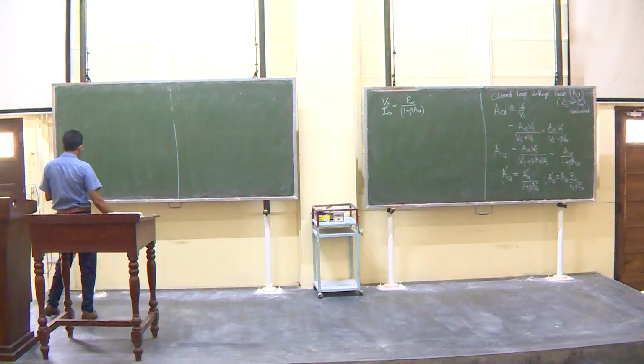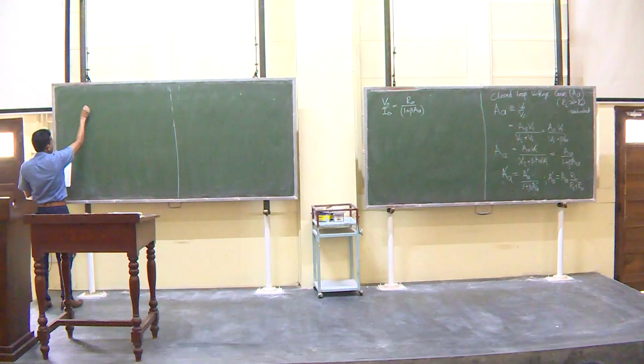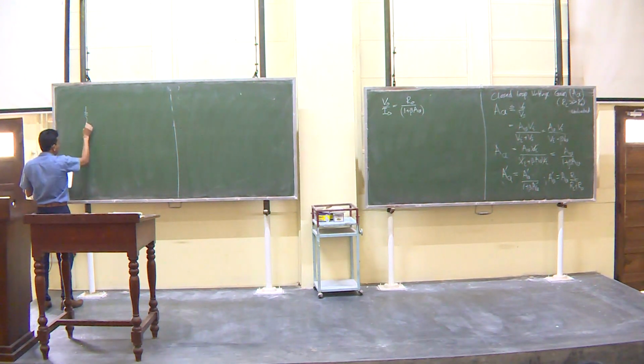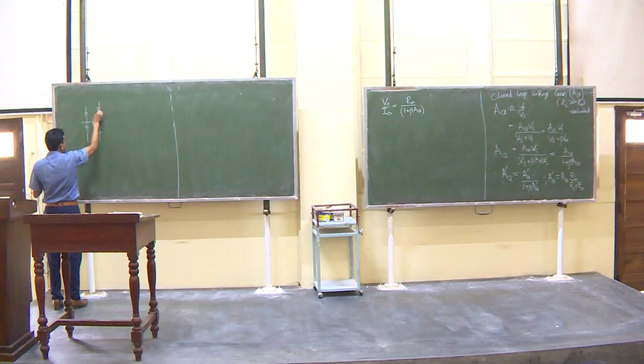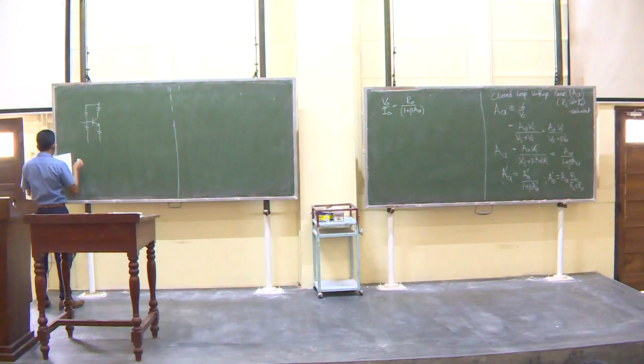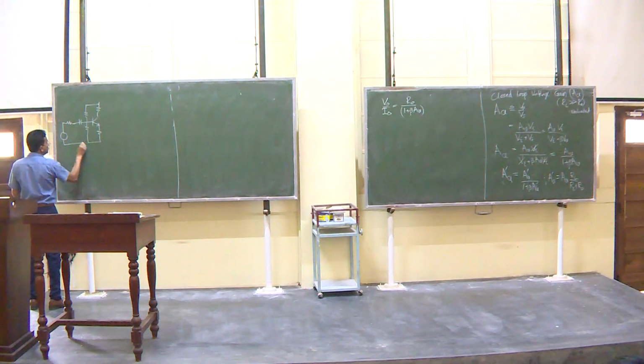So we have a two-stage amplifier. So biasing of the first stage, two NPN transistors. This one has an emitter resistor. This is a common emitter amplifier stage, but with an emitter resistance, which is capacitively coupled through a resistance to a source.